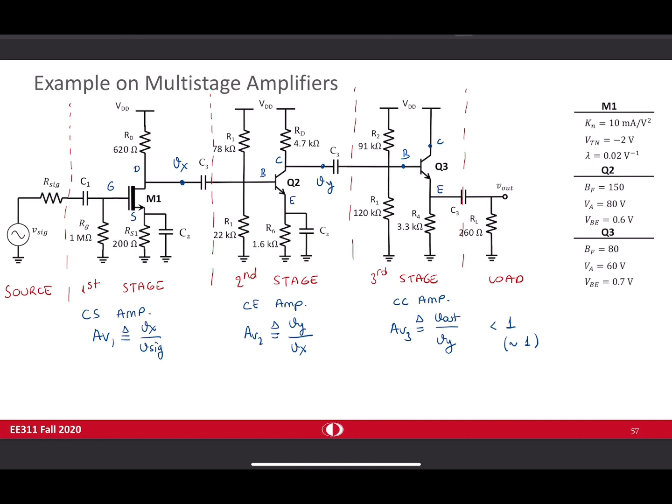So what you do in here, the output resistance of the common collector amplifier is low, so you provide impedance matching. And I have mentioned this in the very early lectures with the audio amplifier example. At that time I was saying that you were trying to drive a speaker, so you need to use a buffer at the output stage. So it's exactly the same thing. You have a low resistance load.